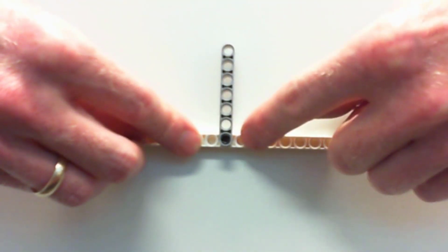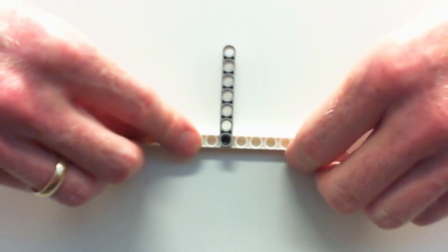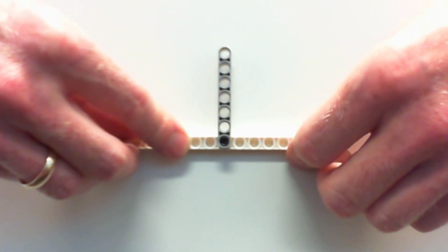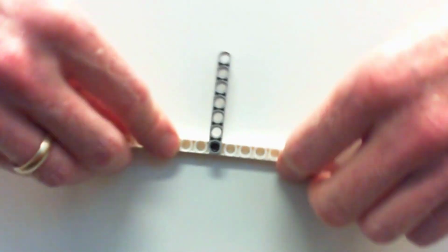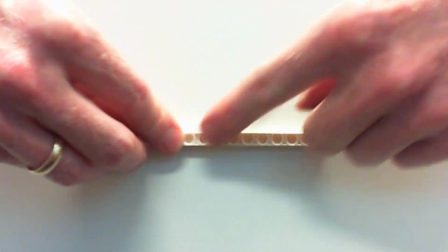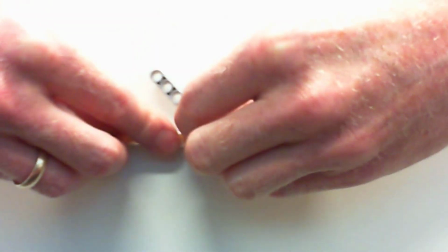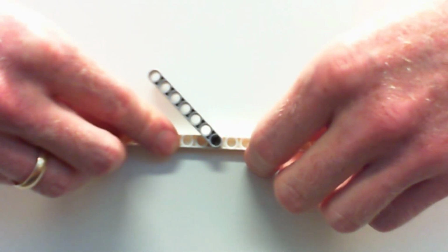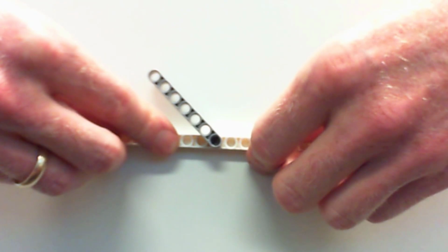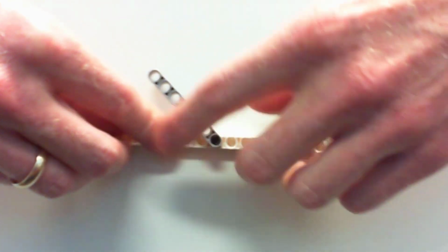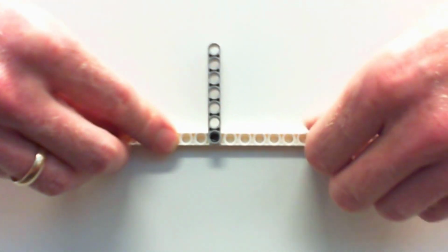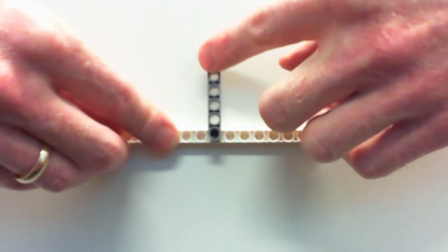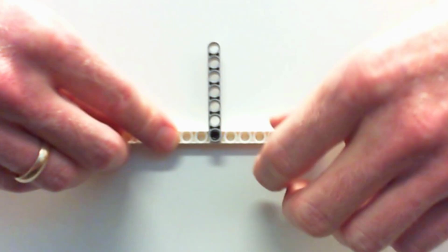Now you could model those as horizontal and vertical. If you wanted to, you could model them as any orthogonal pair of forces that you desired. Maybe you wanted to pick a 45-degree angle, so you picked along this direction and along this direction over here. That would work equally as well. But remember that there's two unknowns, and those two unknowns can either be represented as unknown force components, which quite honestly is the easiest, or also as an unknown magnitude of a force in the unknown direction of that resultant force.